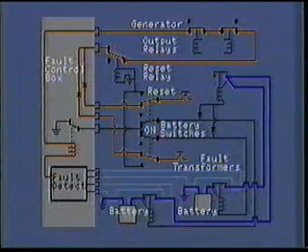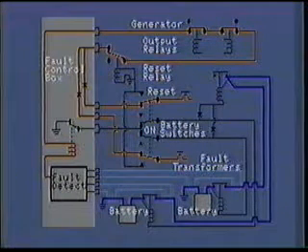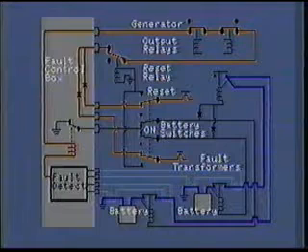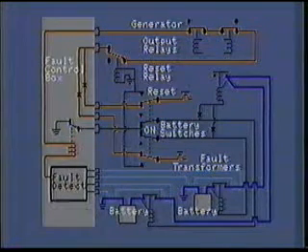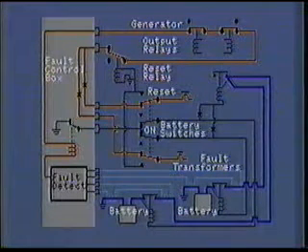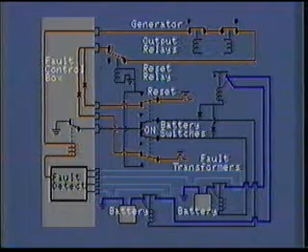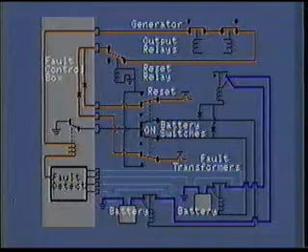These relays are part of a circuit that provides power to a relay coil located inside of the battery fault box. Because no fault in the battery wiring has been sensed at this time, this power will have no effect. But should a fault occur, the power provided through the generator output sense relays is what enables the battery fault box to disconnect the batteries.